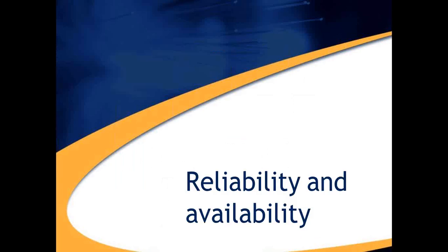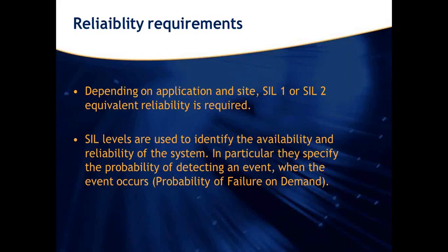So now that we've seen that it's possible to detect ammonia leaks or other leaks with this system, the next question that we received from our customer is how we can make this system part of a security safety barrier. In this case, there is high demand on the availability of the system, and typically in the chemical industry, this is measured with the SIL level 1 or 2.